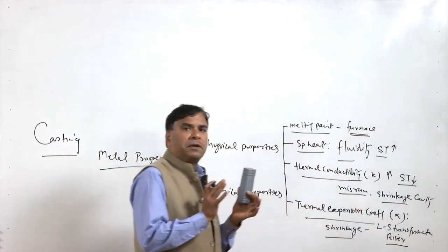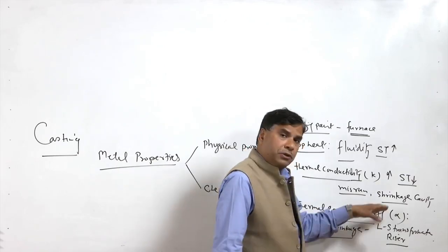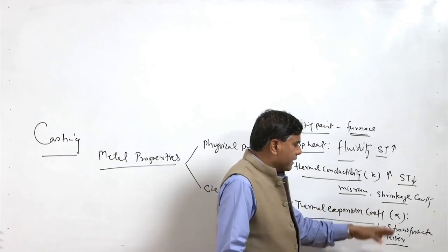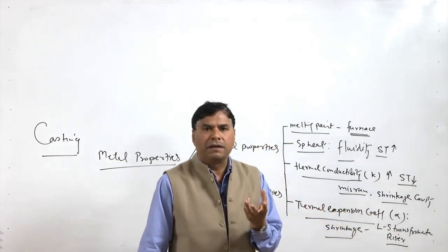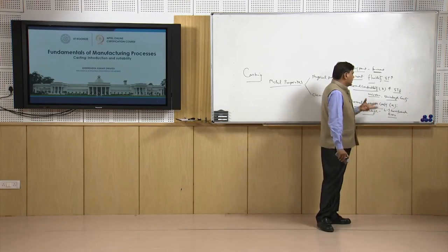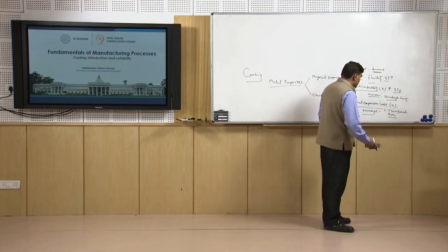What volume of the molten metal is needed to counter the shrinkage related with the liquid to solid state transformation will be affecting the design of the riser, that is, the molten metal which should be there in the riser, so that it can compensate the shrinkage taking place due to the liquid to solid state transformation.